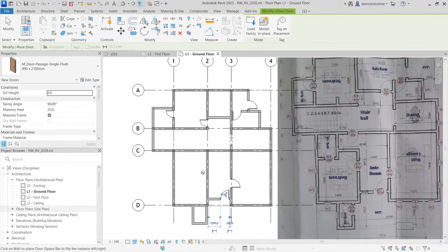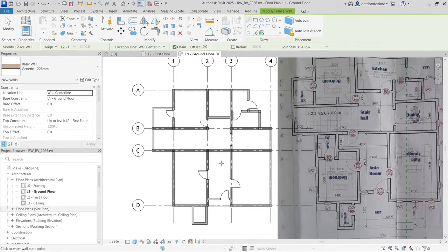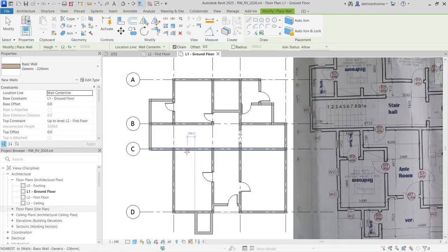And next is to put the door for this room somewhere around here, very close to the main lounge door, almost on the same side. So to fix this part, it's not going to be too difficult. You just have to use a wall. Go to Architecture, Wall, and the wall is 1.3 meters away from this particular line, and also 1.6 meters away from this line. So you can go ahead and stand here and say 1.6 meters. That's 1.6 by 1.3.